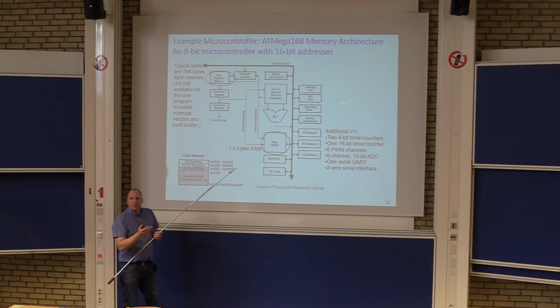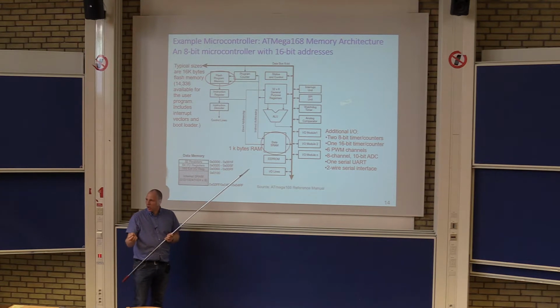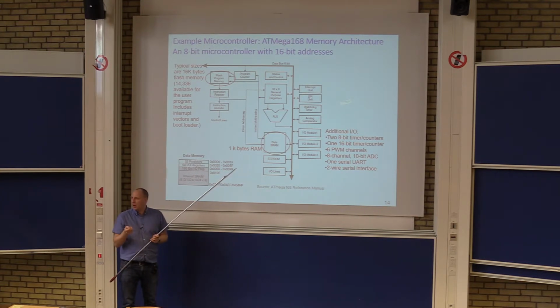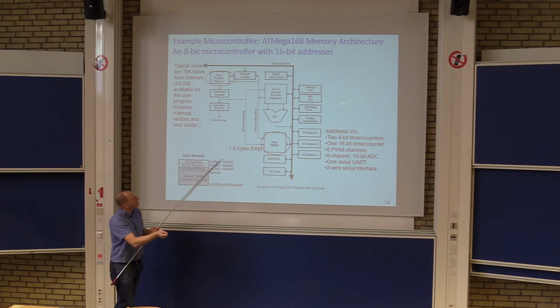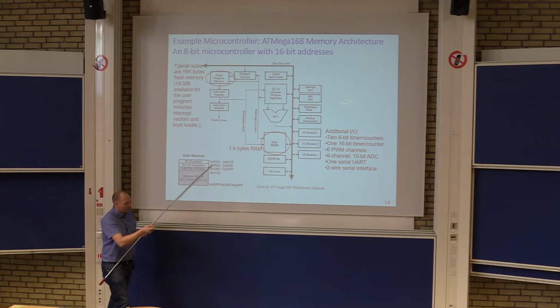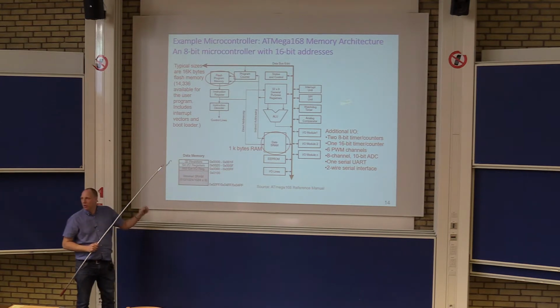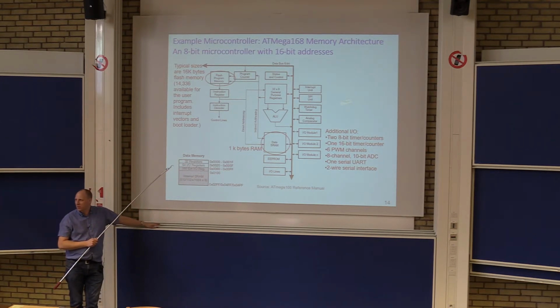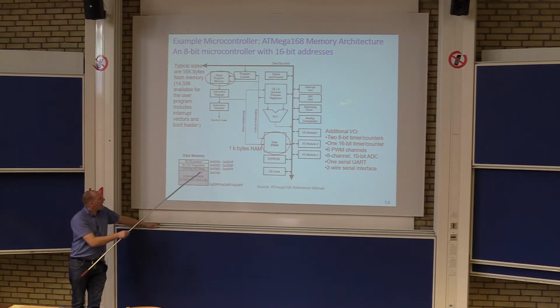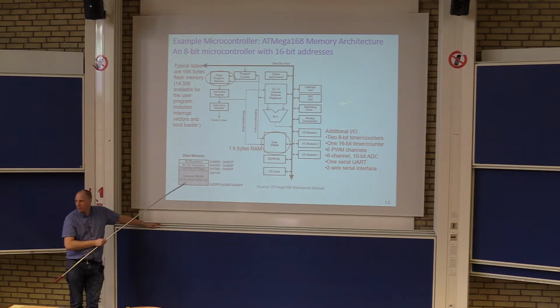So if you have an analog to digital conversion and you would like to read the value after the conversion to a digital number, then you contact this conversion unit and it will actually store its value in one of the registers, at a certain address in your memory.